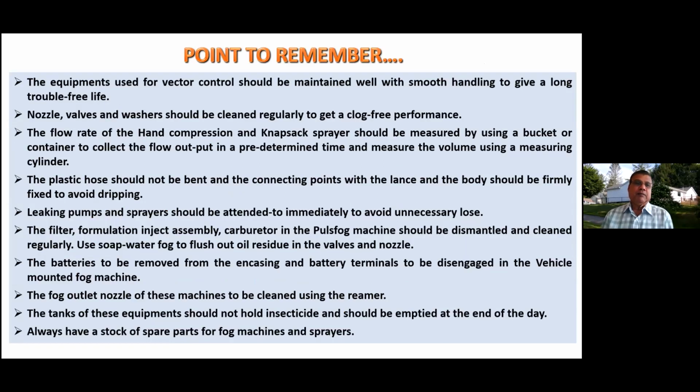So, points to remember. The equipment used for vector control should be maintained well with smooth handling to give a long trouble-free life. So it should be handled very smoothly and maintained well so that it gives a long trouble-free life. Nozzle, valves and washer should be cleaned regularly to get a clog-free performance, especially the foot valve, the lance, the nozzle in the lance.